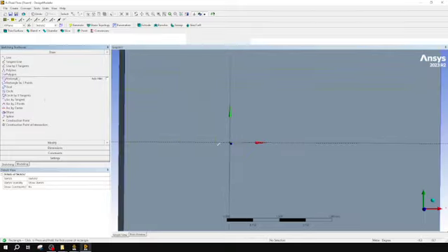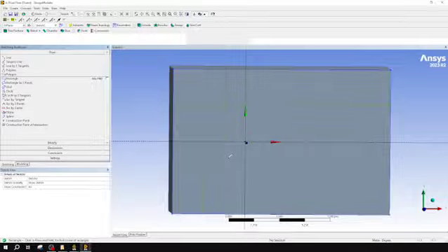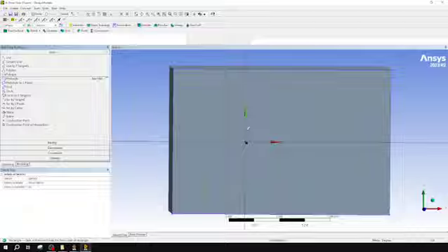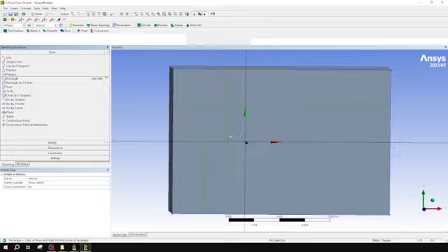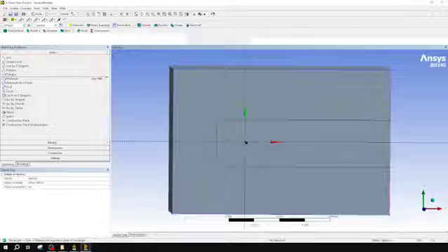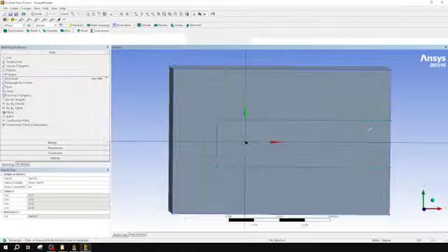So again, just moving over to rectangle, you might have seen that C appear. Anytime it's going to make something coincident, which means on top of a pre-existing line, it'll have this C, just so you know that it's auto-locking to that line. But we don't want that for now, so going to make this front free-floating, but I do want it to span the entire geometry of our box, so I do want it coincident with our back edge.